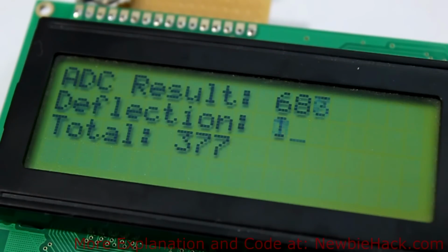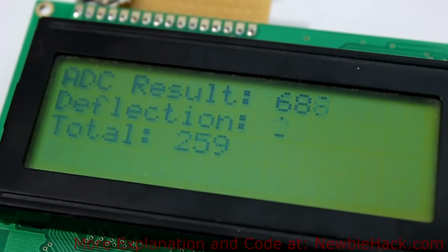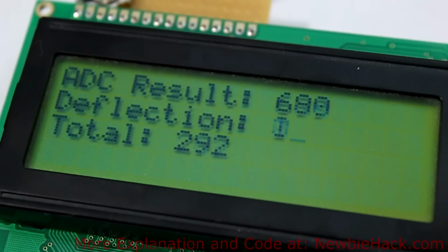So it's not that much better using a 100 microfarad capacitor. It's a lot higher capacitor value, but it doesn't seem to be smoothing it out as much as we would think it would. And from the last video, we knew that there was a lag when we moved the sensor. When we tilted the sensor to get a reading, we would see a lag. I'm tilting it up and I'm tilting it down now. And there's actually quite a bit of lag. So we don't want to use this capacitor. The 10 uF seems to be sufficient.